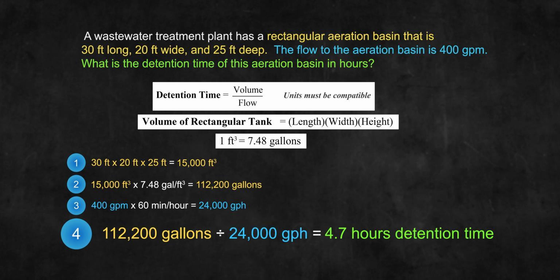Before moving on, I want to stress that the units must be compatible. Detention time questions are fairly common to find on an exam. Don't let them trick you though, as they're deceptively simple. The exam might give you a flow and volume and make you think you can just plug it into the equation. Make sure you understand what units they're asking for in the final answer.